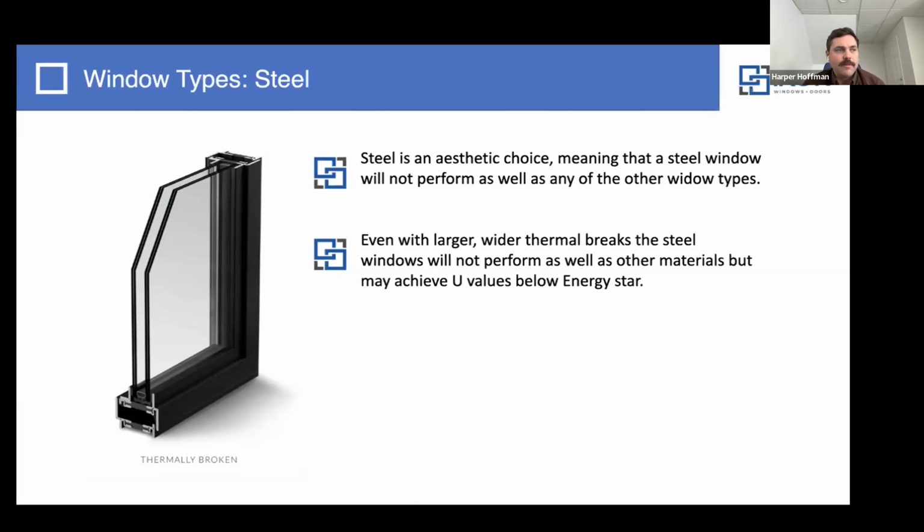It's generally going to be quite a bit more cost-wise, but you're going to have that certain client that wants it, and you can still hit those thermal numbers that you're trying to hit, because it is going to have that thermal break like you can see in the image. And another thing is that the larger you go, you get most of your insulation out of your glass. So the bigger the glass, the better your performance of the window. And steel, where it's so strong, it can have a big piece of glass in it. So you can actually get pretty good numbers with steel.